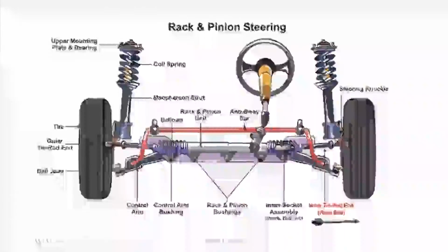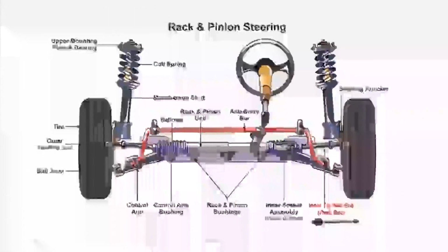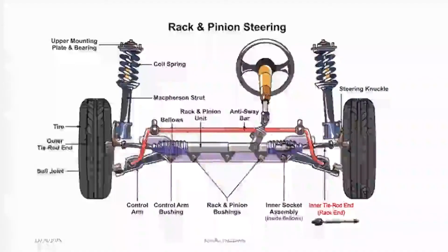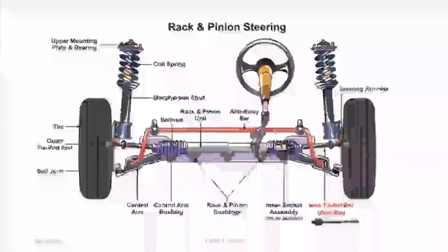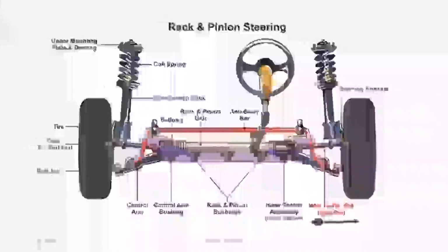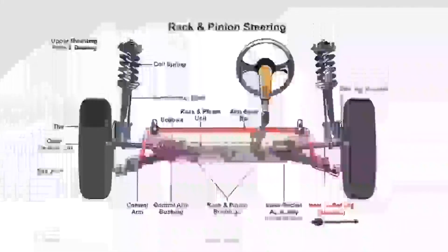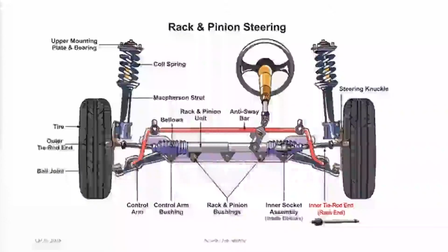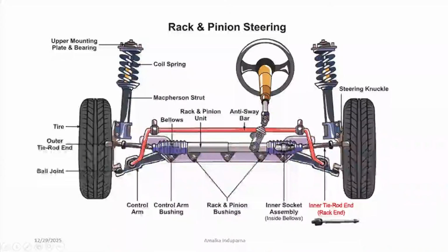And from here in red color, red or orange, I think, we have our stabilizer bar, right? So these are our bushes. Stabilizer bar ends are connected to the lower arms, right? We call it control arm, but more commonly we call it lower arm. Here we have another ball joint, which connects the steering knuckle to the lower arm, right?